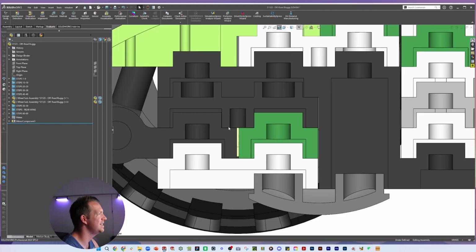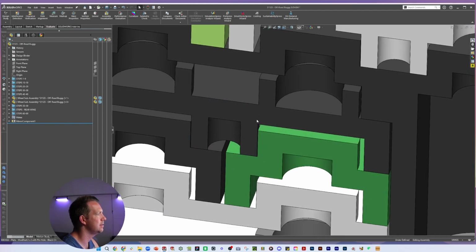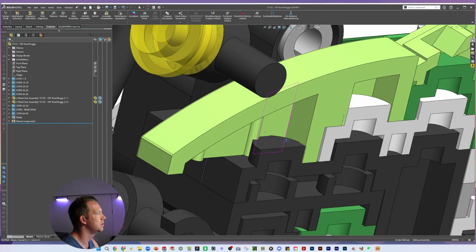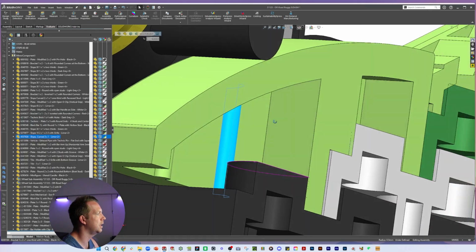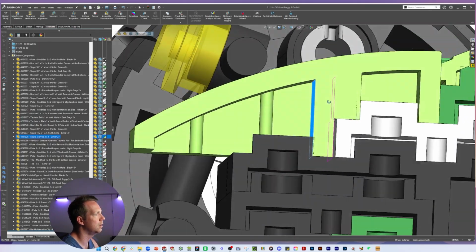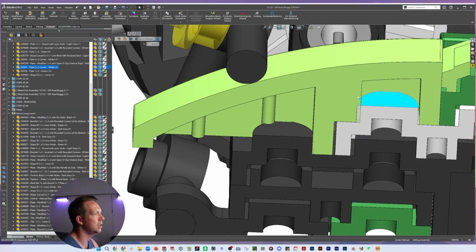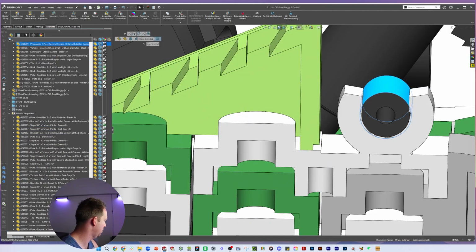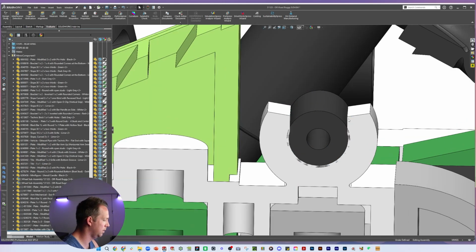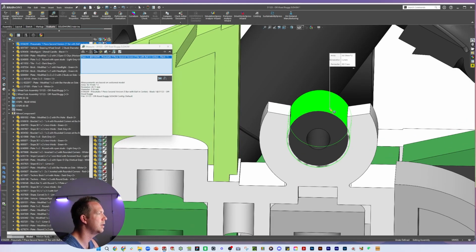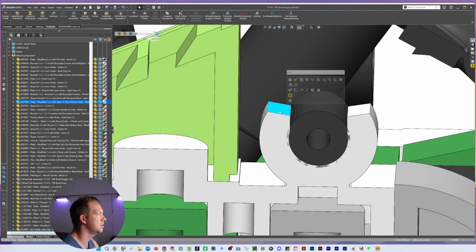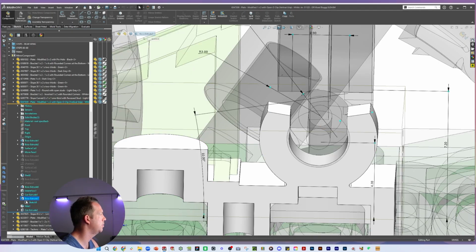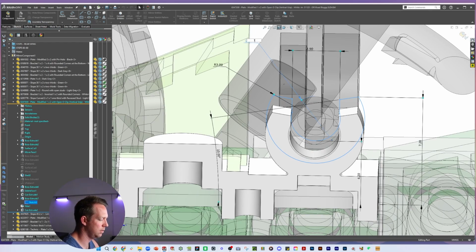So we know that we haven't been perfect with our modeling. So there's a lot of inconsistency with our parts and how they sit. Some look really tight. Some look a bit loose. Some definite interferences, like here, for instance, here. Right, some elements that'll have to change here. Another mistake. Up here, interference around these pins. Interesting. Right, so there, it's like, well, I probably measured that one correctly, which means this one's probably wrong. You know, if I just click on this one, click on that shape, where I've got 3 in the middle, let's just change that to 3.2.